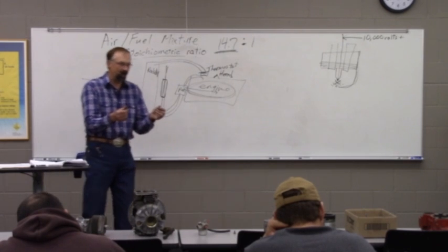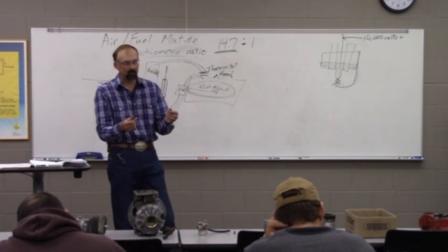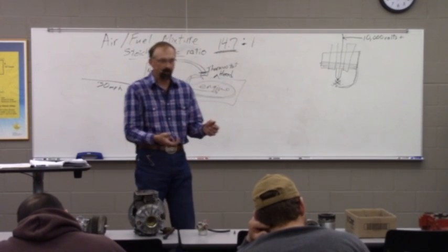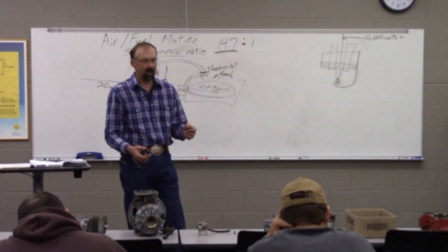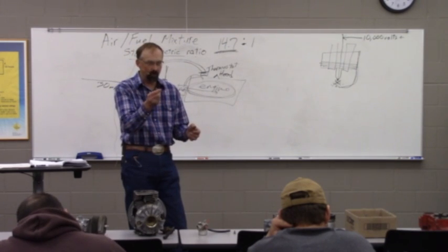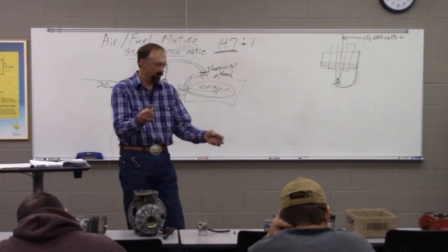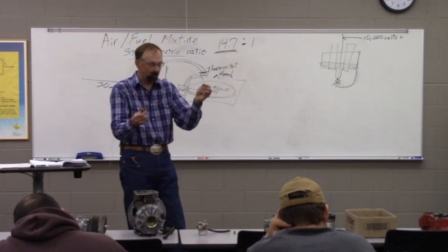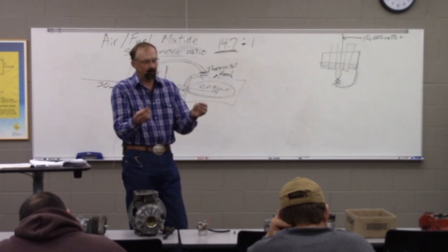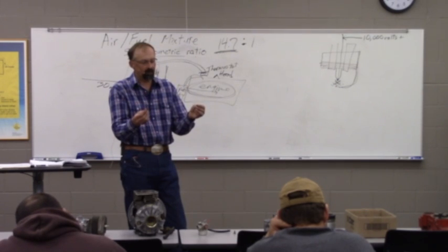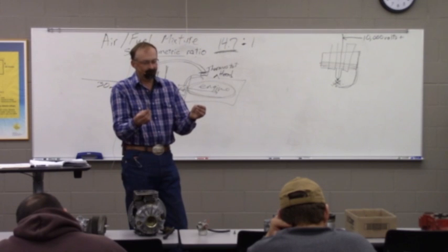Same thing with the automatic transmission oils. The regular Dextron, which is mineral based, typically, even if you were being really nice to that automatic transmission, you rub it between your fingers when it had 20 or 25,000 miles on it, and you rub brand new with the same exact oil, you could feel a dramatic difference in the lubricity of it, how slick it was. With the synthetic oils, you can go twice that long in a lot of cases.